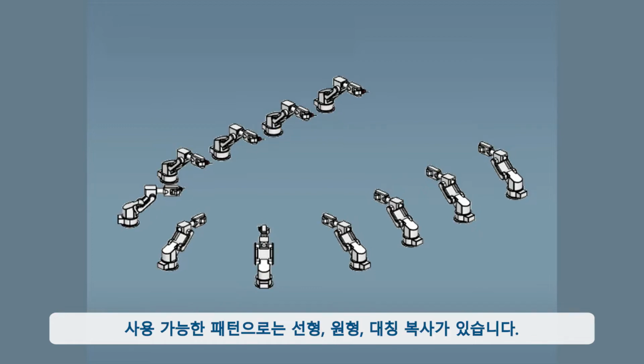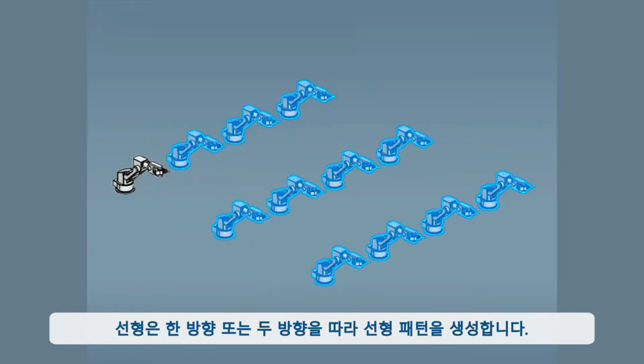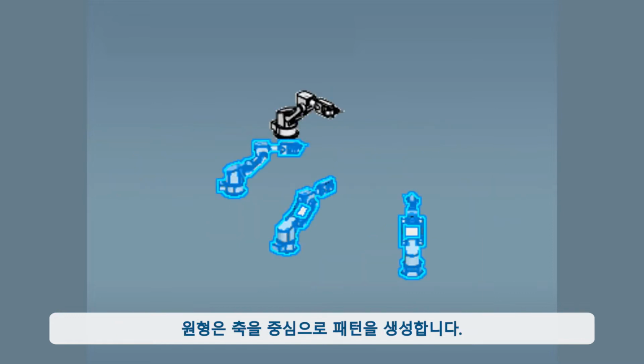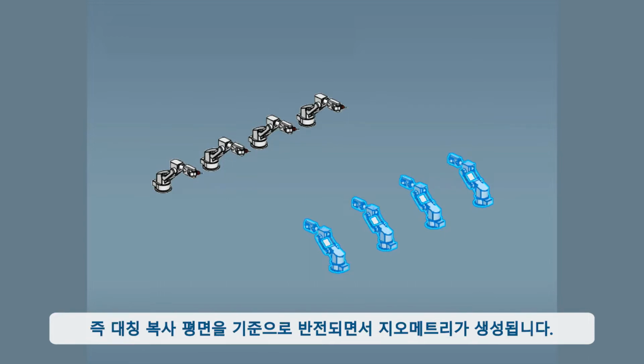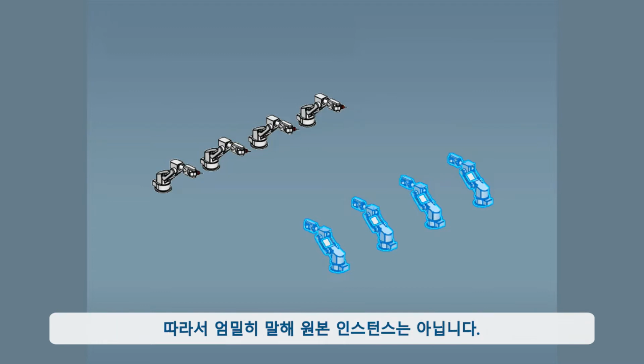The patterns available are linear, circular, or mirrored. Linear creates a pattern along one or two linear directions. Circular creates a pattern about an axis. Mirror creates a pattern across a plane. Note that mirror creates opposite-hand versions of the components, geometry that is reversed across the mirror plane. They are not true instances of the source.